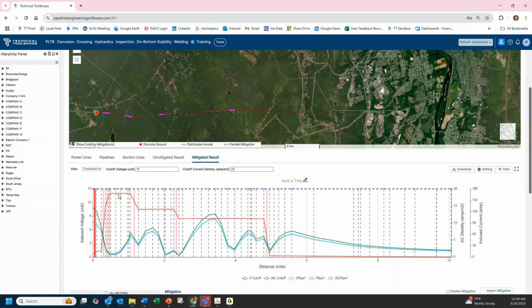Like I say, I'm a big fan of copper because it lasts a long time. I have a system in there over 20 years, and it has just minor pitting on it, and it's draining heavy current day in and day out. What I mean by heavy is 50, 60 amps.